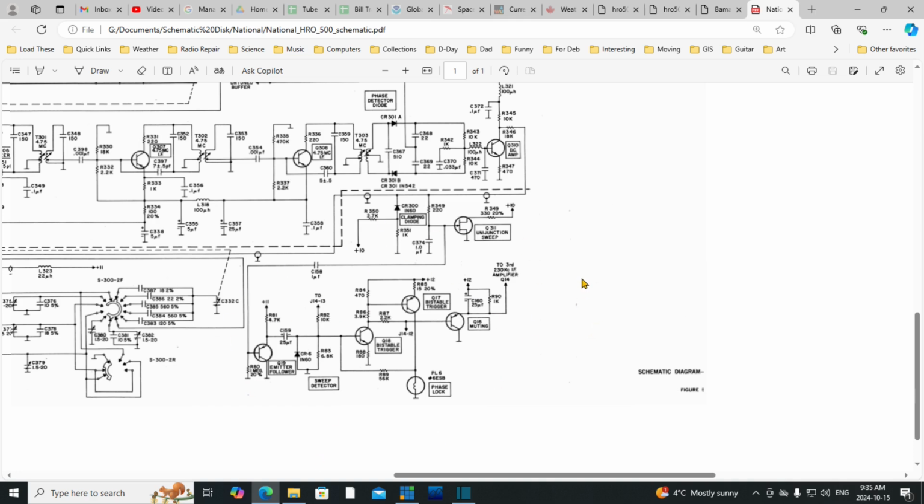Okay, getting back to this, because I'm rambling now. And again, I just have kind of a smoky, foggy feeling about how all this works, so you don't have a tight grip on it. So by dropping, we can read this in the written part. It actually says something about the voltage here dropping below 11 volts. And when it gets below 11 volts, the amplifier Q14 shuts off. That cuts off the output of the IF. There's nothing left for the radio to produce in the speaker.